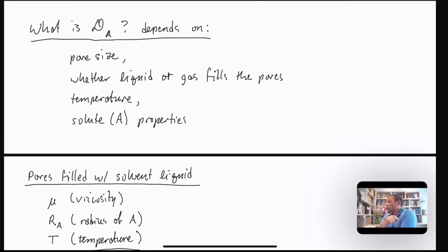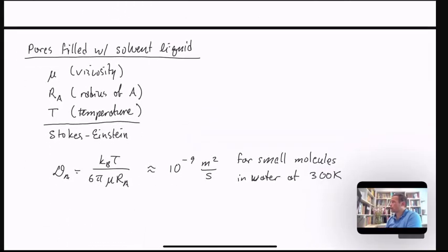Well, it depends on what medium fills the pores and how large the pores are, and of course some other properties of the fluid in the pores and the molecules themselves. If the pores are filled with a liquid solvent, then that solvent is going to have a viscosity, and the molecules that are diffusing in the pore and in the solvent are going to have a radius, which we'll call Ra. And of course, there's a temperature as well, and that affects the viscosity,